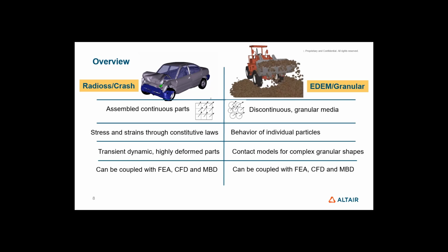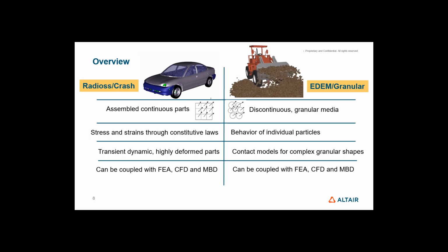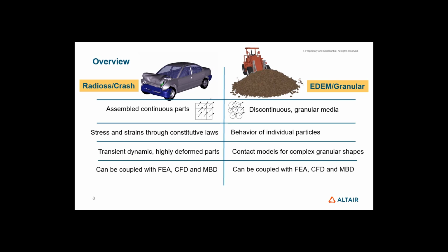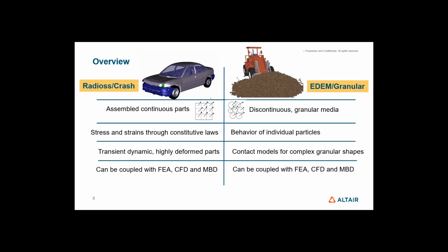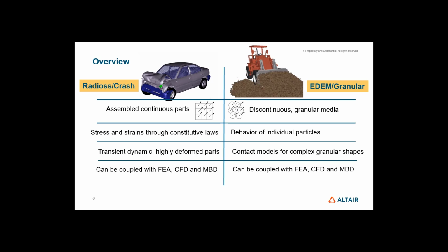Here we compare Radioss and IDEM solvers. Radioss crash is used to study shock problems. It is suitable to simulate the behavior of assembled continuous parts by finite element method, where we want to compute the level of stress and strains and to understand if there is a rupture or not.